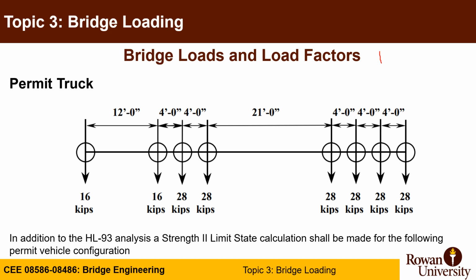HL93 is a combination of the HS20 truck, plus lane load, or your tandem, plus lane load.